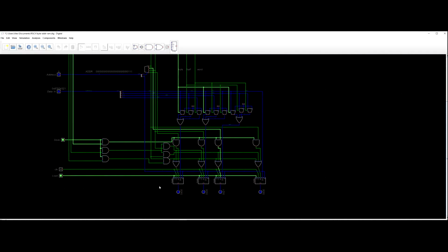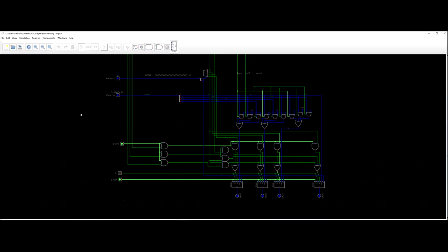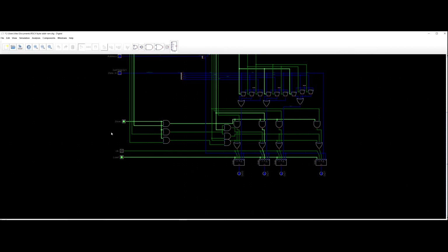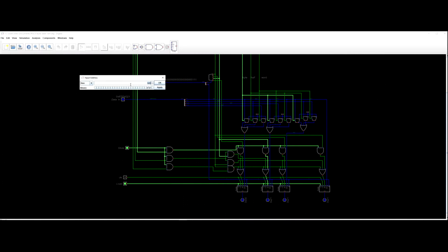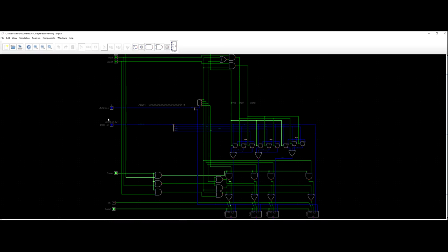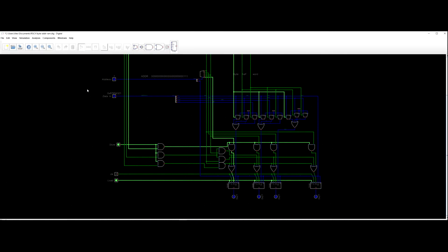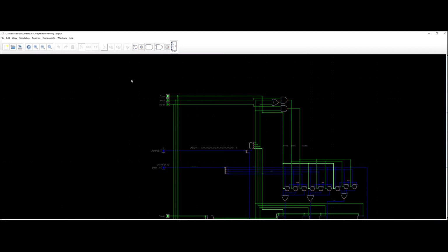Okay. And so now I should be able to move that around. I should be able to put that at address 4. Clock. I should be able to put 21 at each one of those. 6. Okay. Clock. Oh, there we go. 7. Okay. Clock. Okay, cool. So that's working. I was able to put 21 there in each one of those spots. I was able to write a byte to any one of those positions.